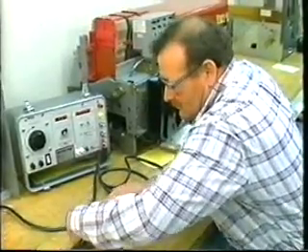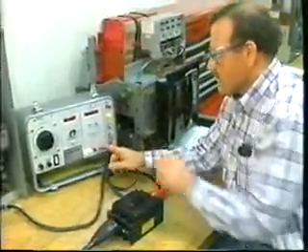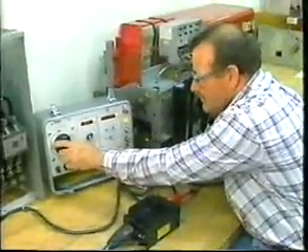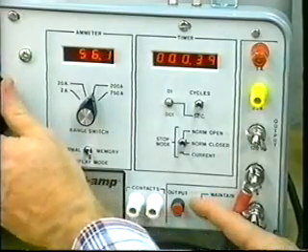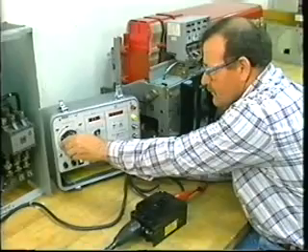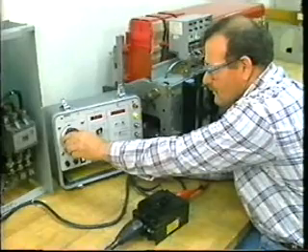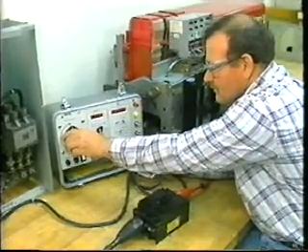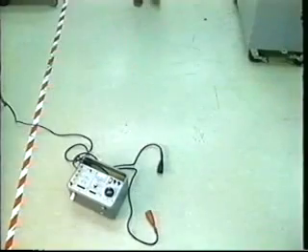The pulse method requires the following steps. Connect the circuit breaker to the equipment. Apply current in short pulses of 5 to 10 cycles. Increase the current on each succeeding pulse until the circuit breaker trips. Occasional errors do occur due to current offset. This distortion is known as DC offset or asymmetrical.